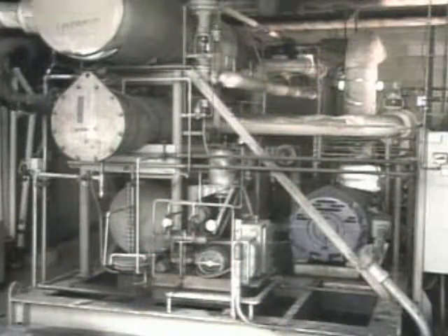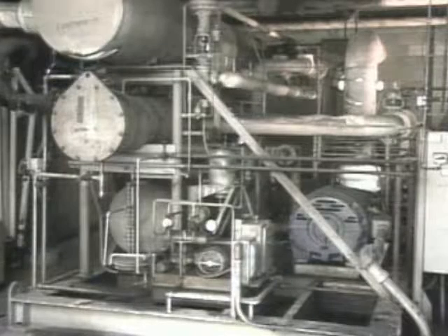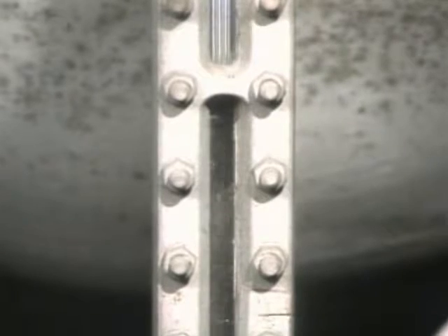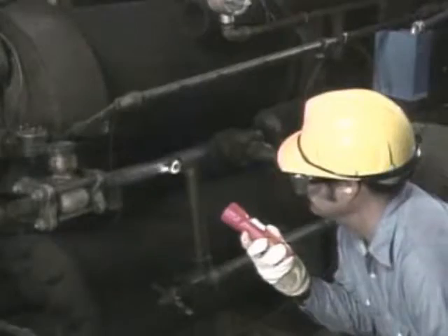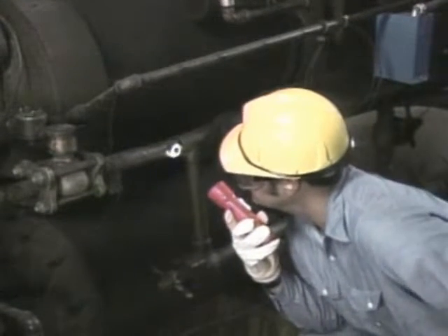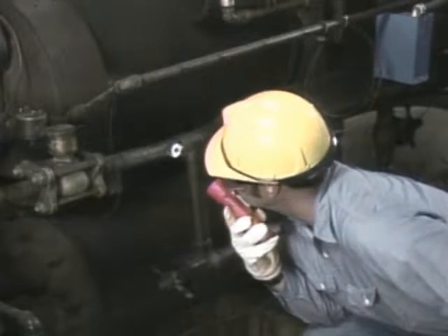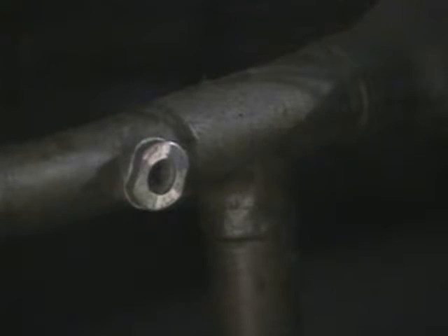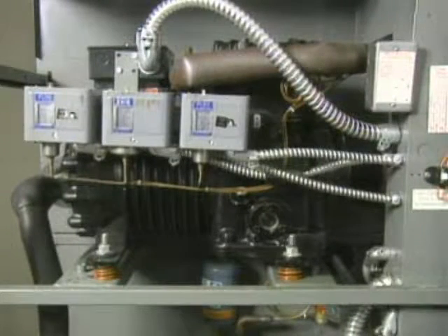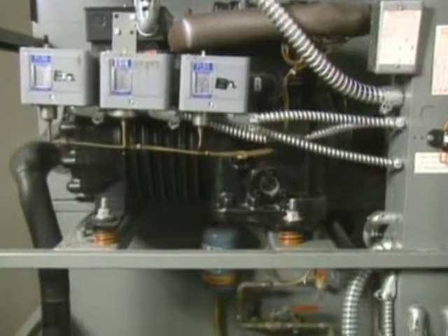Ideally, a vapor compression refrigeration system will run efficiently and practically by itself. Sometimes, however, problems may occur. One of the more common problems that can affect a refrigeration system is an improper amount of refrigerant. The amount of refrigerant can be determined by checking a level indicator on the receiver or by checking a sight glass on the receiver outlet. When the amount of refrigerant in the system is correct, the refrigerant seen in the sight glass should be clear. If there's not enough refrigerant, the refrigerant may appear cloudy and it may contain bubbles. Another indication of too little refrigerant may be a continuously operating compressor.